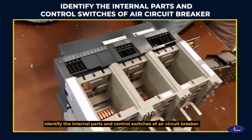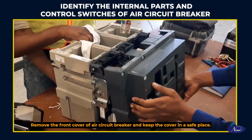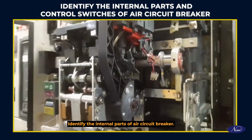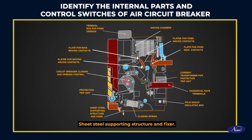Identify the internal parts and control switches of the air circuit breaker. Remove the front cover of the air circuit breaker and keep the cover in a safe place. Identify the internal parts of the air circuit breaker. Sheet steel supporting structure and fixture. It supports all the parts of the ACB mounting.